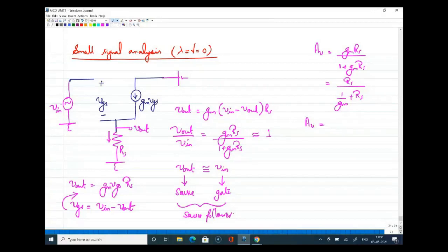or common source or common gate, for all the amplifiers, the gain without lambda and gamma, just with the ideal MOSFET, you have straightforward ways to write the gain. In the case of common source, you know that the resistance available at the drain divided by the resistance looking into the source, RD by 1 by GM, was written as GMRD, that is the gain of the CS amplifier.